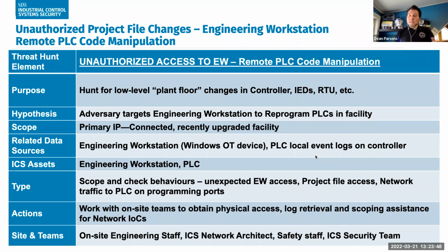Now, beyond what we've seen in the past for our data sources, obviously the engineering workstation, which is commonly a Windows OT device, we definitely have to consider the logs in the controller. A lot of times when doing assessments, we do see that the controller has logging enabled, but it's only to the local device. And sometimes they're not enabled at all. So it's really difficult to hunt at that lower level. Something to keep in mind as we go through.